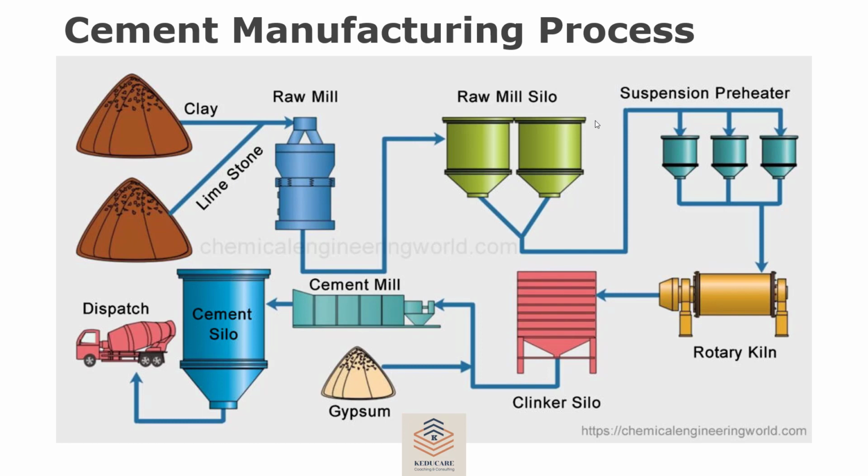Before the argillaceous material is stored, it is first washed with water. So this clay is first washed with water. Both the materials are then channeled to mill equipment where they are intimately mixed in desired proportions to form a paste. That is in the wet process. So in the wet process, it is washed with water before a paste is formed.